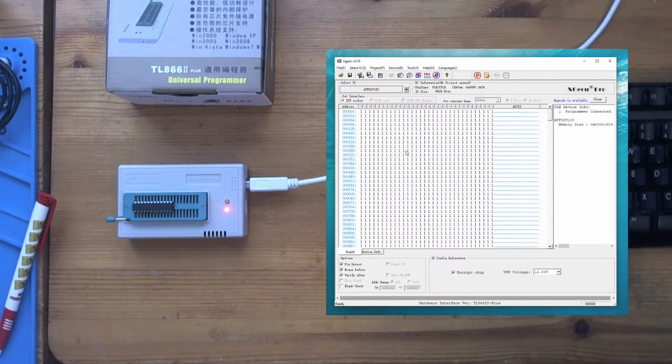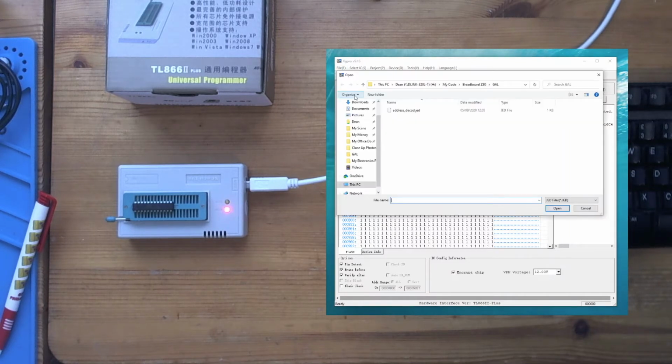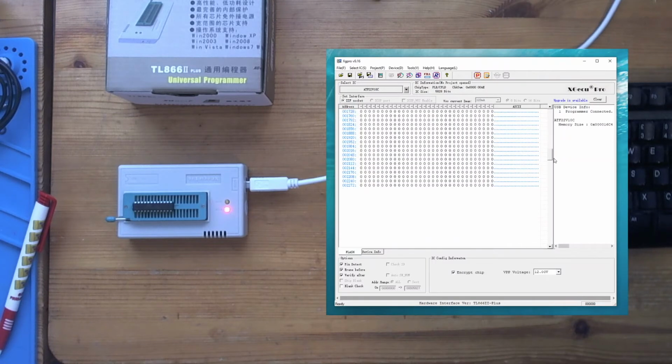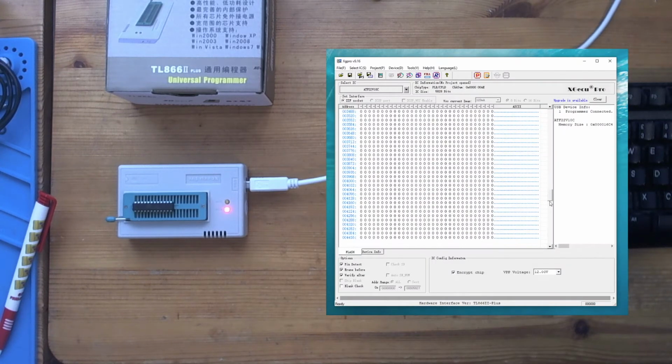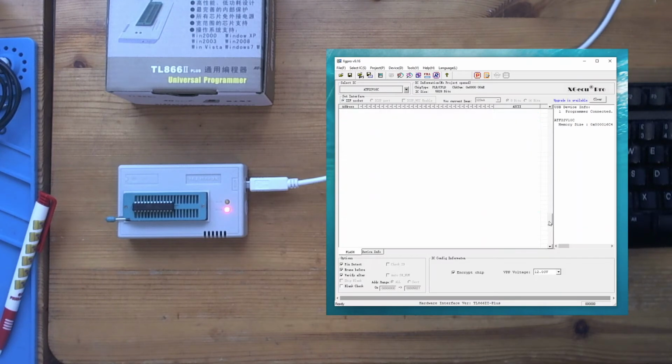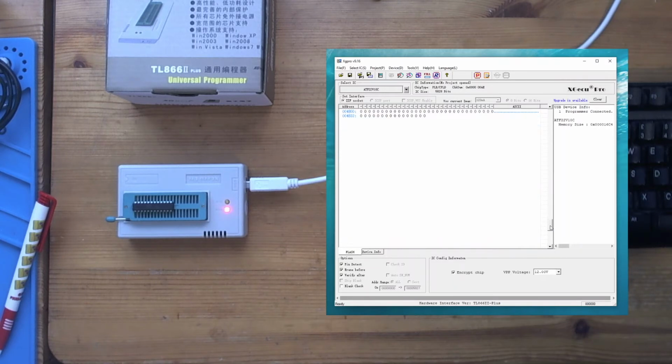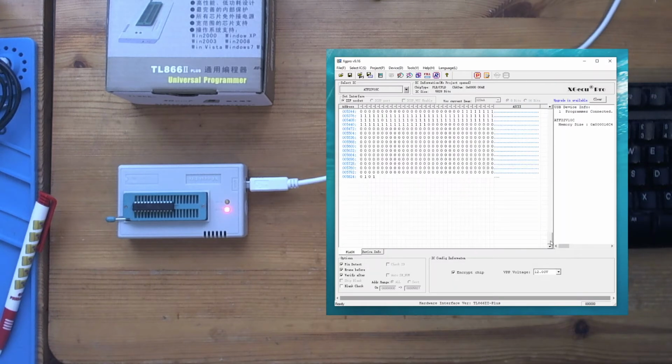The next step is to load up the JED file. That's the fella. So if we scroll down, it's all zeros. Should be some ones somewhere, hopefully. There we go. That looks like my logic, but it looks like some logic anyway. Technically it looks like just ones and zeros, but I assume that is my logic. So the final step is to program it. So here we go.